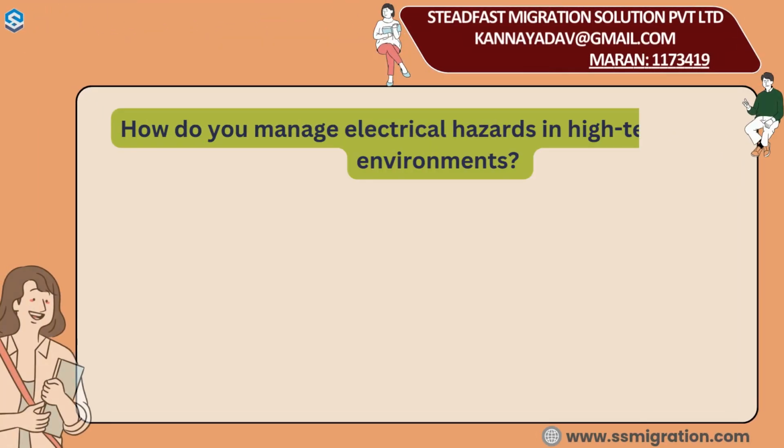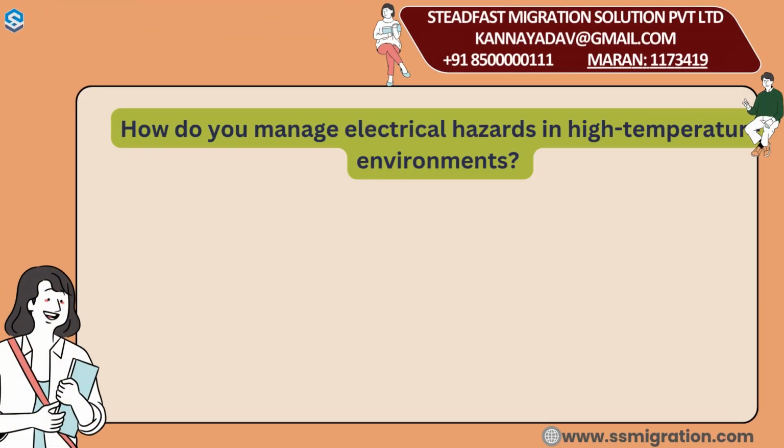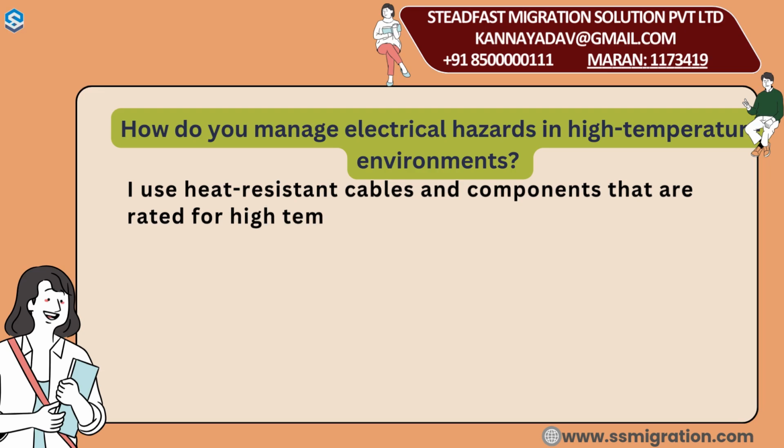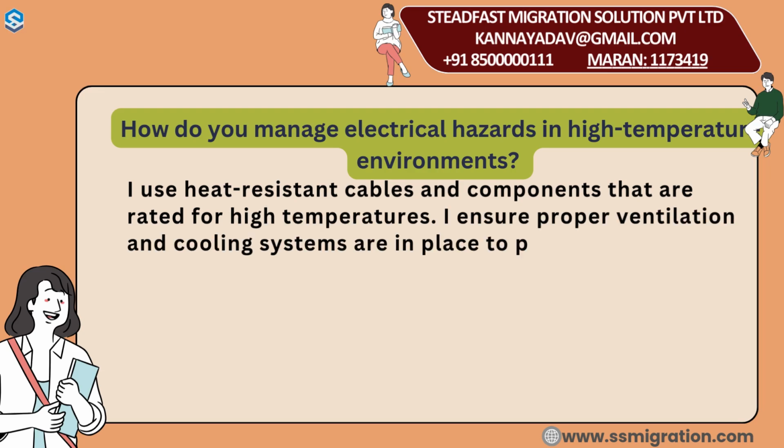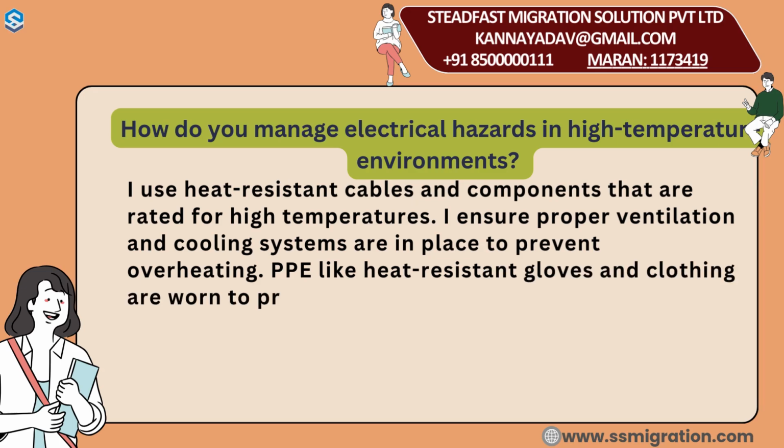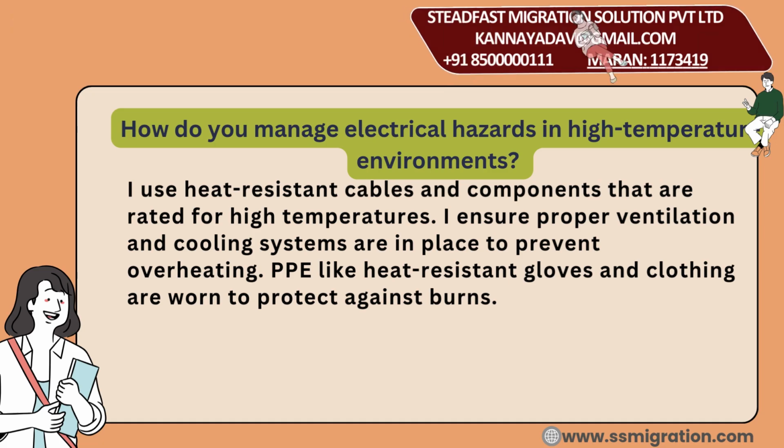How do you manage electrical hazards in high temperature environments? I use heat resistant cables and components that are rated for high temperatures. I ensure proper ventilation and cooling systems are in place to prevent overheating. PPE like heat resistant gloves and clothing are worn to protect against burns.